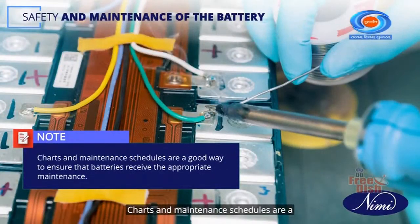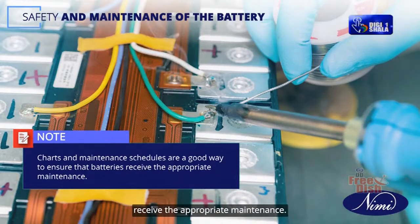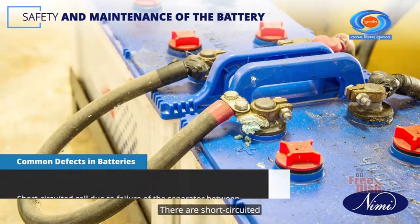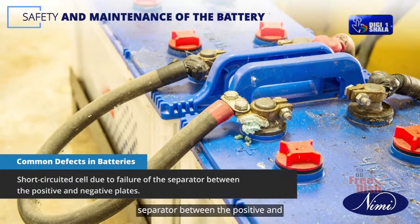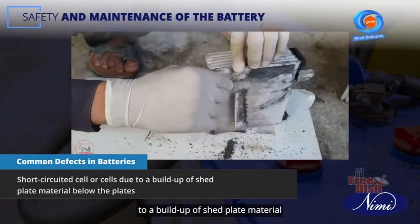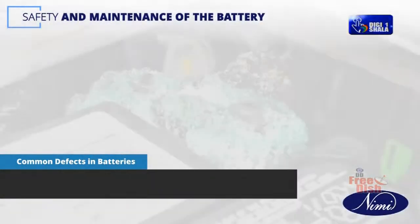Charts and maintenance schedules are a good way to ensure that batteries receive the appropriate maintenance. Let's briefly go through common defects in batteries. There are short-circuited cells due to failure of the separator between the positive and negative plates, short-circuited cell or cells due to a buildup of shed plate material below the plates,